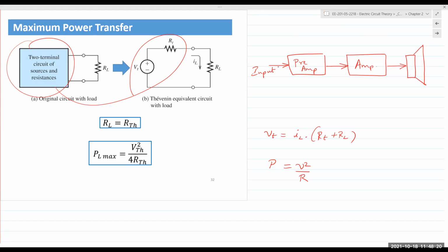Now, impedance is a term we will look at in chapter 5, but for now, think of it as resistance. So the amplifier spec sheet is telling you that in order for the amplifier to function correctly, your speaker needs to have an 8 ohm impedance, 8 ohm resistance, if you will. The earphones that we use, at least the wired ones, have an impedance of 32 ohms. AirPods, I haven't looked it up recently, but I believe they were either 16 or 32 ohm impedance, 32 ohm resistance.